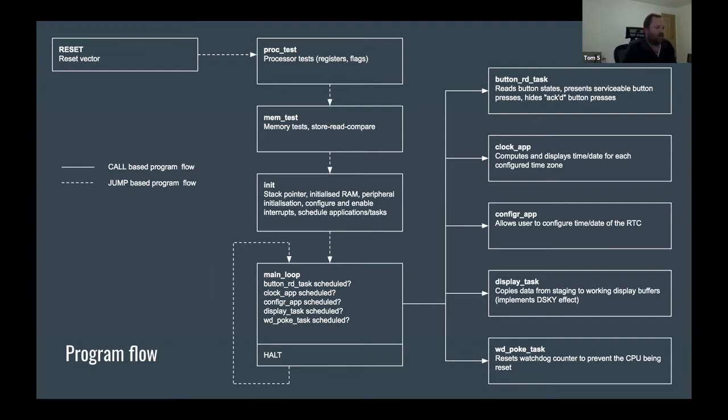But the memory test would always succeed. So I'm not really sure if it works or if it was just something that the memory test couldn't actually detect. It does write about 4 or 5 different values into RAM, but perhaps it requires even more values to be written and read to pick out this problem that it had.